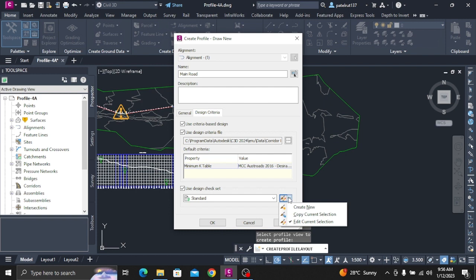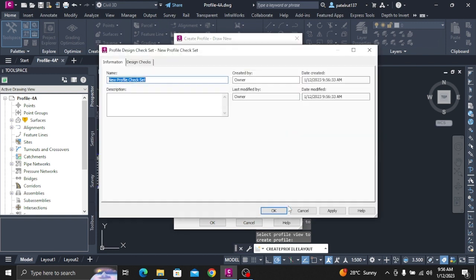Maximum, 670.00 foot. Split Profile View, selected. Click Next. On the Profile Display Options page, clear the Draw checkboxes for all profiles except Surface 1 and Layout 1. In the Layout 1 row, select the Split at option. This option specifies that the split occurs at the appropriate elevation of the layout profile and ensures that the entire layout profile will appear in the profile view.